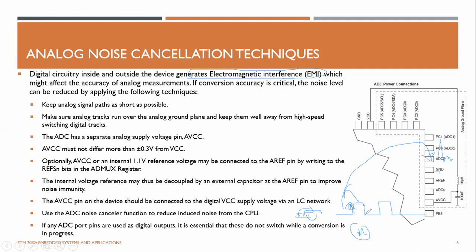So due to this fast switching of digital pins, the noise of these nearby digital pins can affect your ADC reading. So you have to be careful. That's why these kinds of recommendations are provided by the manufacturer.